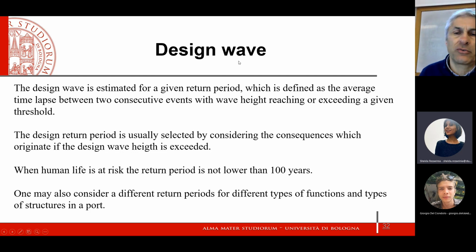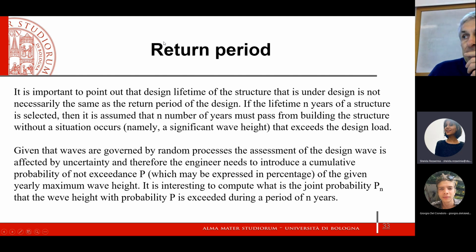But in general, you have to look at regulations. Regulations give you indications or restrictions or formal constraints. You can increase the return period if you see that this is not really a problem to oversize a structure. You cannot decrease it. Okay.